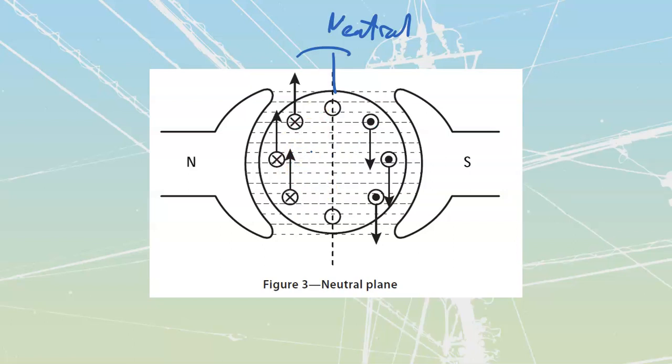Okay, armature current is also going to give us a little bit of armature reaction. We talked about this when we were looking at DC gensets, that armature reaction is this thing that happens where I'm going to create a north and a south on my armature itself, just based upon the way that I have got my currents traveling through there.